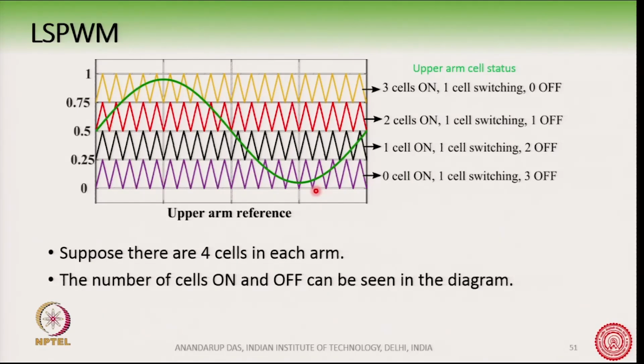In the power circuit, we are trying to fabricate this part of the voltage waveform. From the arm we are trying to fabricate this part of the reference waveform. Ideally, the actual arm voltage in the power circuit should be an exact replica of the reference voltage, because when we give the reference voltage we are asking the arms to produce exactly a replica of it, but amplified in the power circuit.